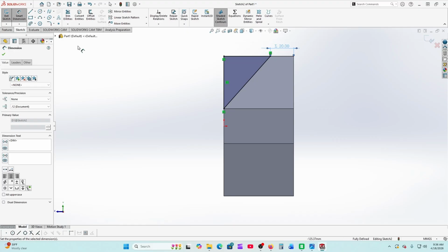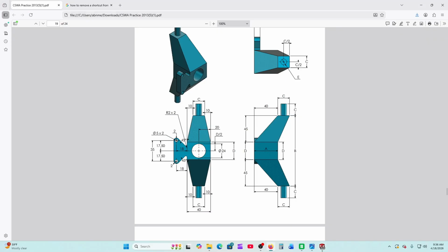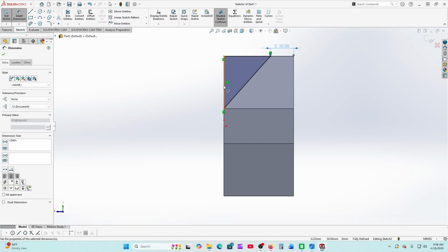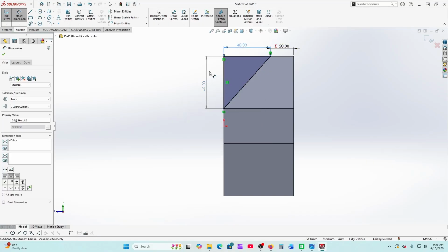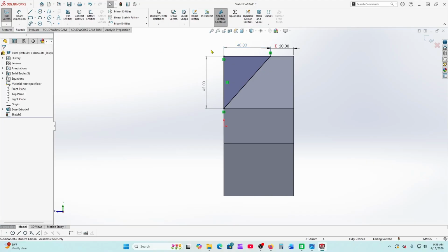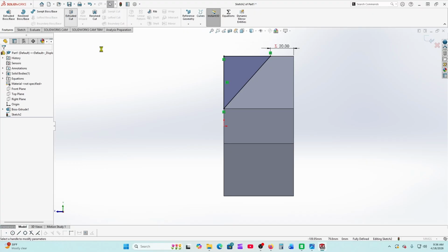And then if we actually go in here and dimension everything else, so we're looking at 45 and 40. So our dimension, 45, is driven based off of everything else we have. And then this was 40. So everything is coming out exactly the way we needed. We're just using the global variables to lock everything in place. So we didn't have to dimension these, but they are here.